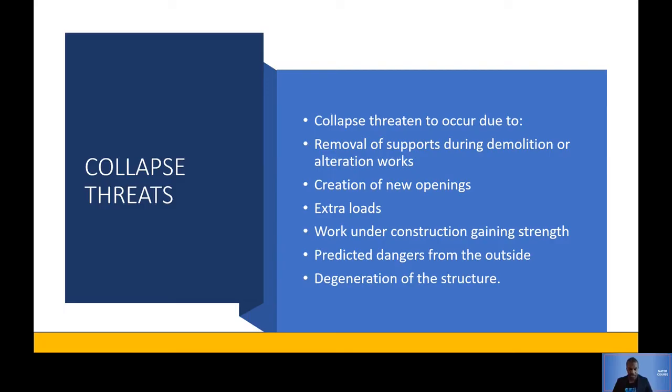That means that if there are a lot of things being constructed in a building and you need extra strength, you provide shoring. Predicted dangers from the outside. Maybe it's a windy place, there's going to be a storm, so you might need to put shoring in ahead of the storm.